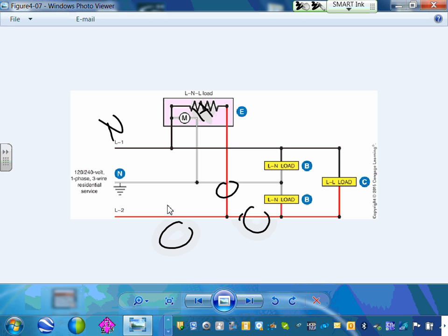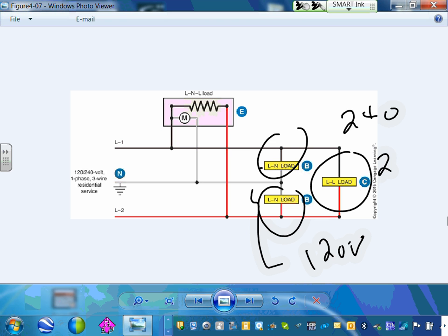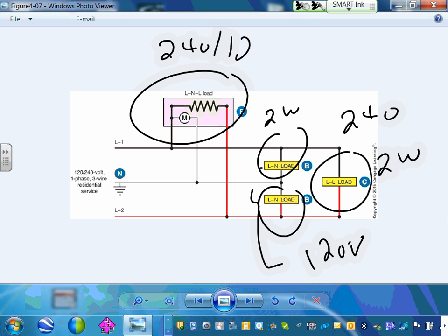We talked about the 240/120 single phase system, guys, two loads. When you have single phase 240, the system that we use in the US, you can feed two types of loads. This load, guys, is called a 240 load. This load and this load are called what? 120 loads. So be aware of that. Unique system, and there is equipment that takes only two. This is two wire. This is also two wire. An equipment right here that's actually 240/120.